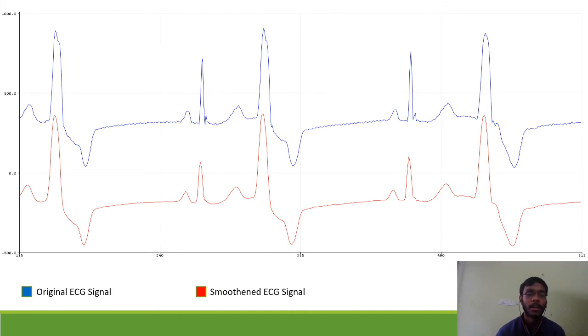Now here you can observe a thing. If we keep L equals to 8, that is the block size equals to 8 in the moving average filter in this region, then these peaks will get cut off at some frequency. It will be cut off because if I get a point here and then a point here, then I am taking the average of all, so I won't get this peak.